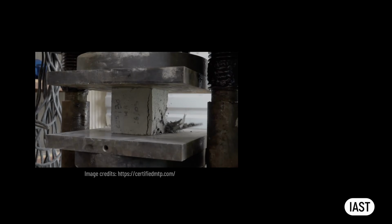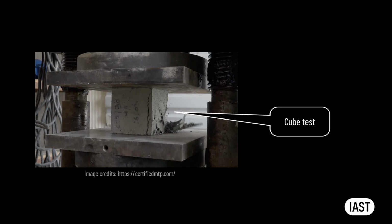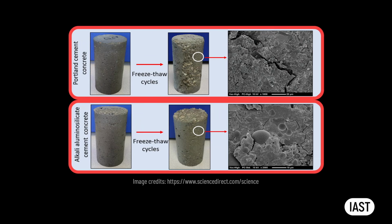In the Applied Facade Engineering course, we talk about the cube test, which is designed to test initial compressive strength, and the life cycle test of the concrete. Both tests are necessary for newly built precast concrete facades. In the case of existing facades, these tests could be substituted by a structural engineering report prepared by a qualified structural engineer who visits the building and describes any visible defects of the structure.